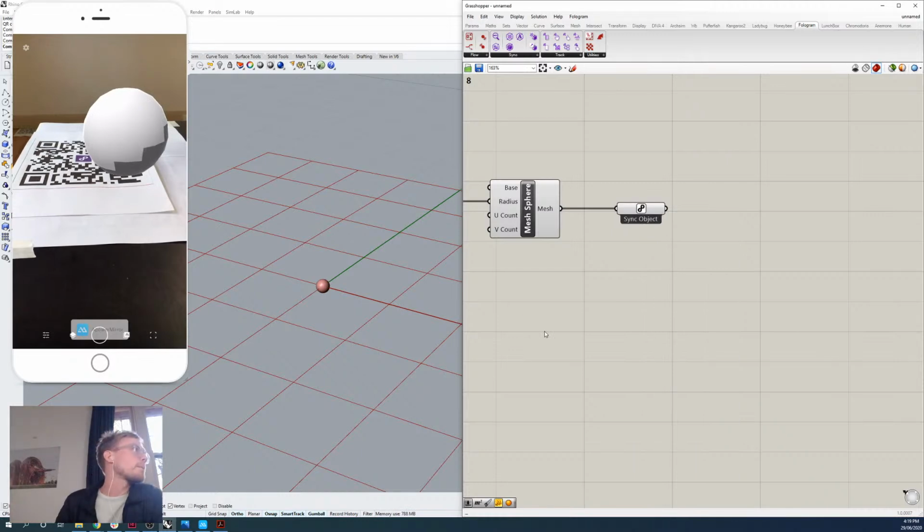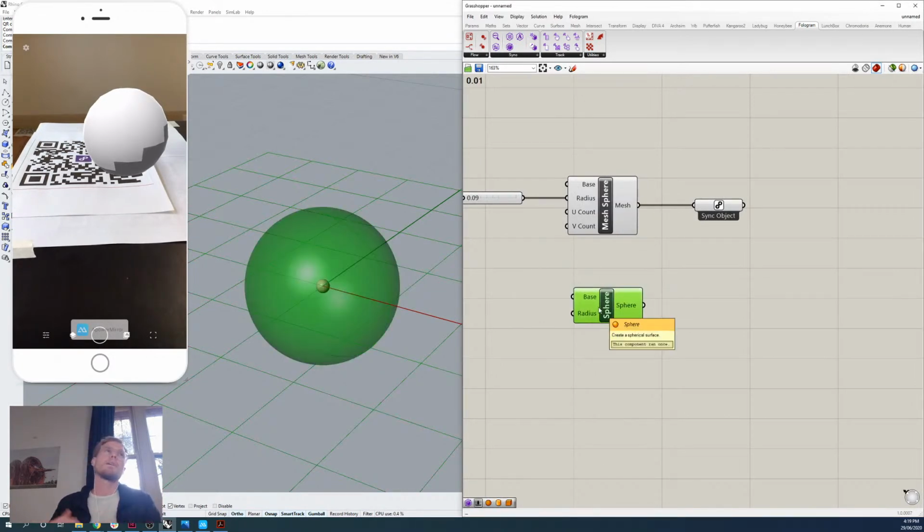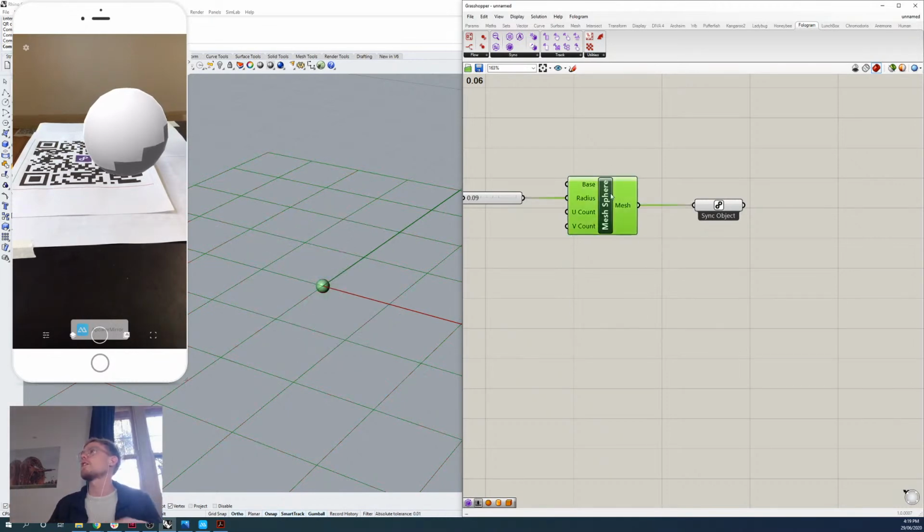Oh yeah, a couple of people are having the same issue that I was having, so it might be a bit of a bug. Basically, because the sphere component is NURBS geometry, it's not a mesh, I think what Fologram's doing in that instance, which it doesn't usually do, is downsampling that to be a much lower poly geometry. So go ahead and maybe just swap it out to a mesh sphere for now, and you should get the mesh sphere appearing like I do.